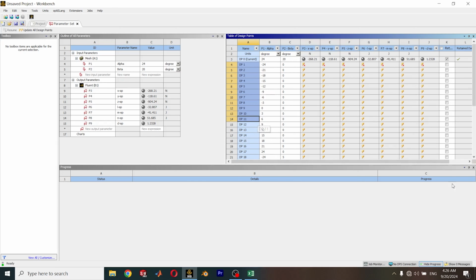So abort the process. The last available design point is going to be 10. So start from 11. Of course, before you start, save your project. Okay, now we are done.